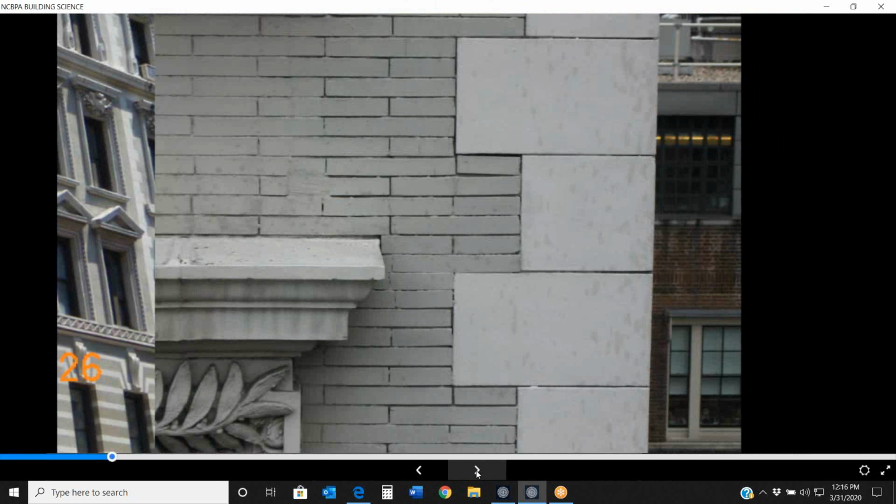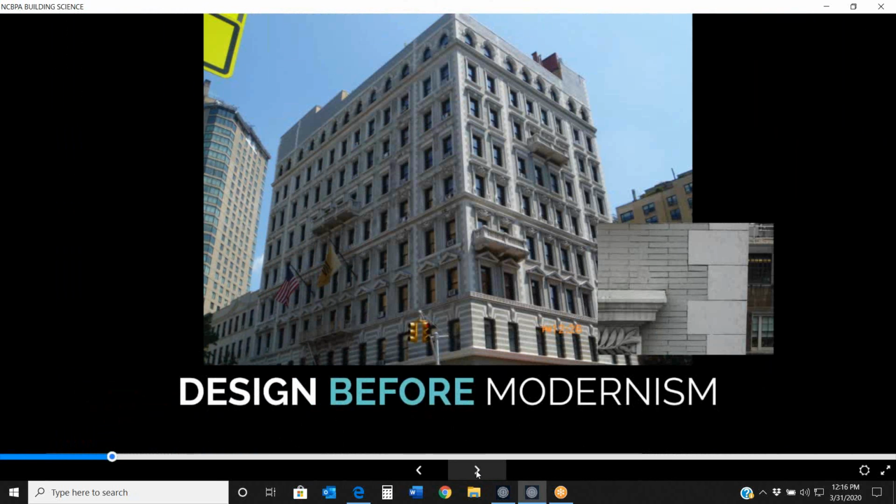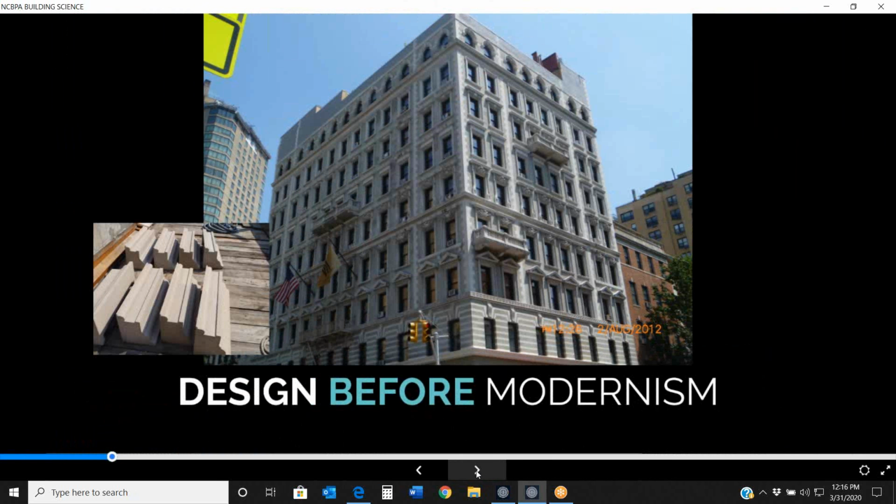Talking about corners, when you look at cornerstone, we used our material, kind of the old adage, the cornerstone, putting it wisely. We used the strongest materials where our buildings were going to take the most load, specific to the elements. Here you can see massive stone cornerstones, and because of that, we can use some of our less expensive and less robust materials, this brick, inboard of these corners. We were designing for our environment and how buildings were going to be challenged.